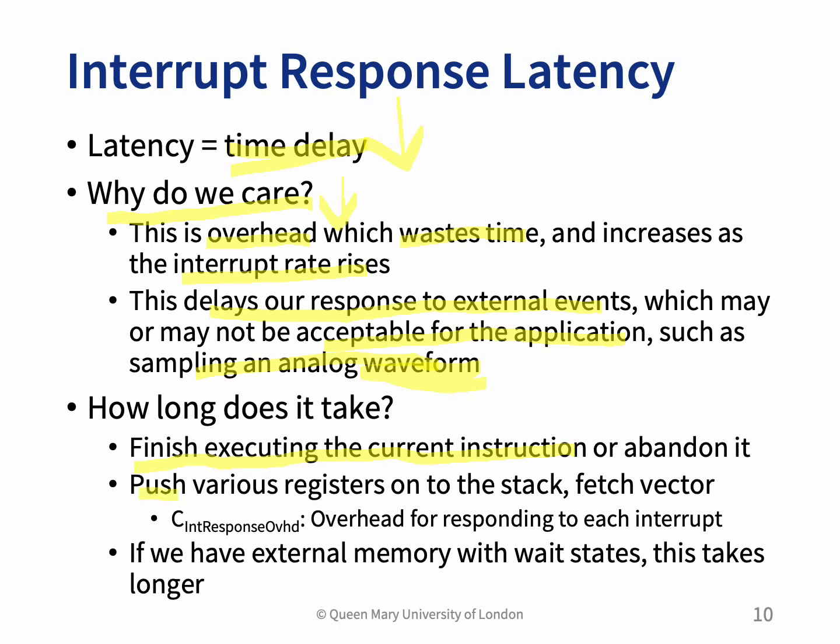We can also push the various registers onto the stack and fetch the vector again, right? So this is just an example. You do not need to memorize it. So there is response overhead, overhead for responding to each of the interrupts, right? So this is another mechanism for us to quantify the overhead.